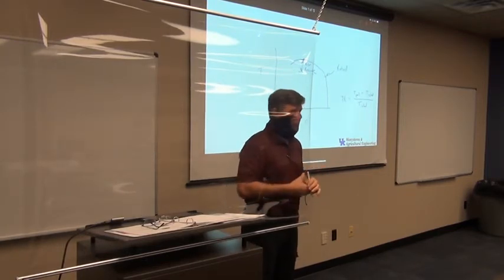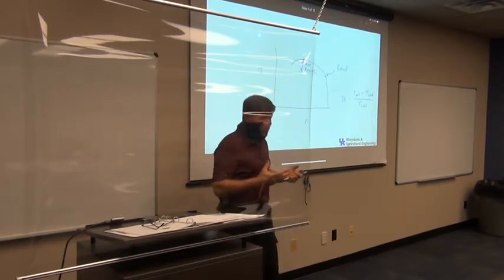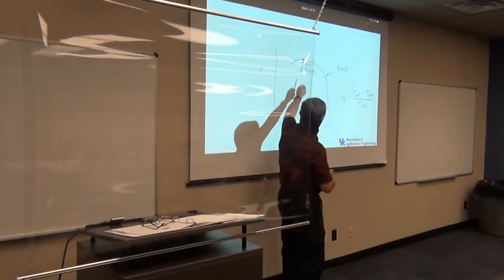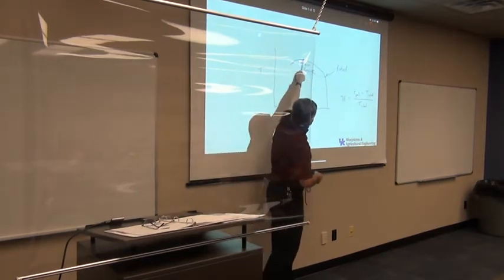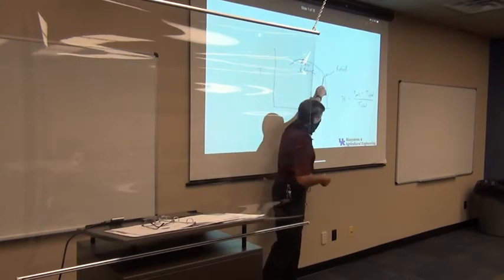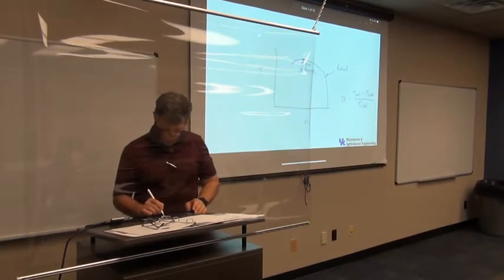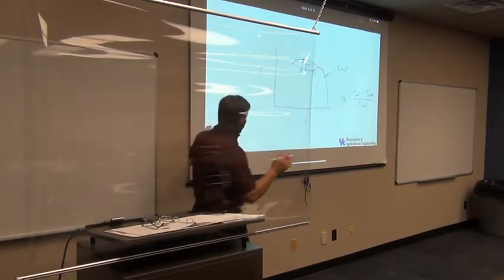We don't have time to go into a lot of the performance differences, but gasoline engines, spark ignition engines in an automobile or something like that, typically do not have a whole lot of torque reserve. And that peak torque happens pretty close to the rated point over here. So a gasoline engine might do something like this, where I get a torque rise and it looks something like that. So its curve is going to be a lot shorter.